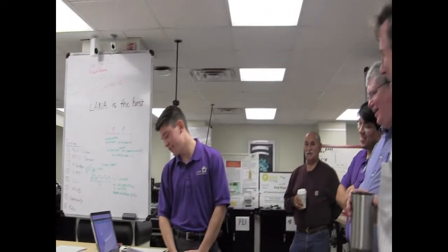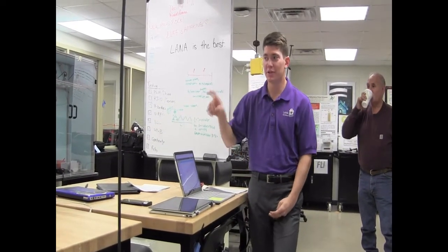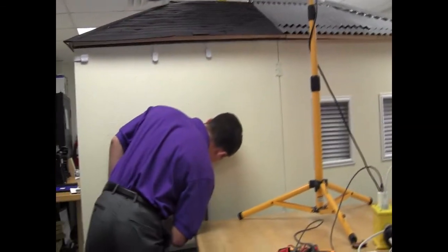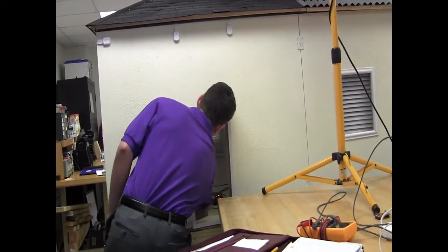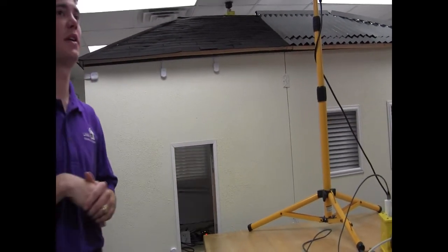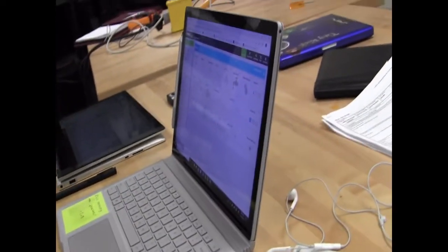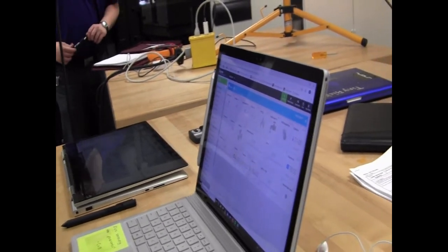All right, so test 13, he said jokingly. Test 13 is our water level sensor test. So there's a cup of water on the interior of the house. I taped it to the wall again. So the cup of water is right here. Our sensor can measure water levels up to 1.5 inches. Essentially I'm going to show that the sensor's in water. We're going to dip it in the water, and we're going to see that it senses that there's water. And it does not do varying depths.